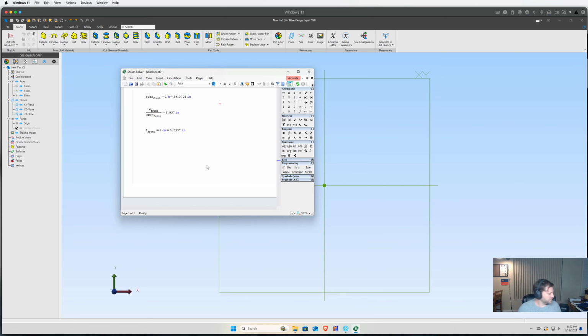But I think I'm going to take a shortcut for simplicity's sake, and we will say that we're going to have a rectangular cross-section wing, because it's not going to be completely uniform at cross sections. It'll be thicker at the front, thinner at the rear usually to make a good airfoil or hydrofoil. So it's going to be kind of a wedge shape, but we're going to take a really first crack and say, you know what, we're just going to approximate it as a rectangular beam right now.